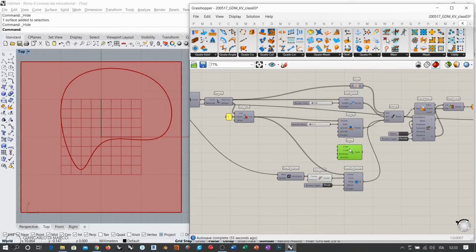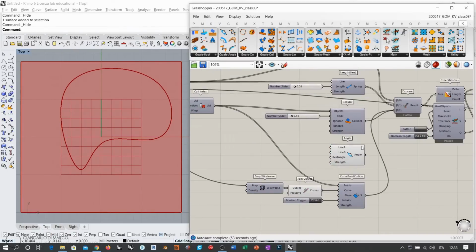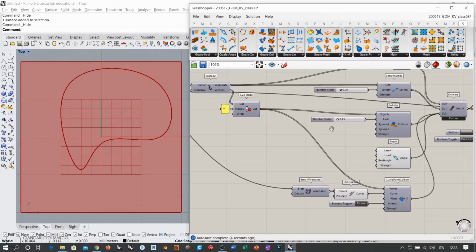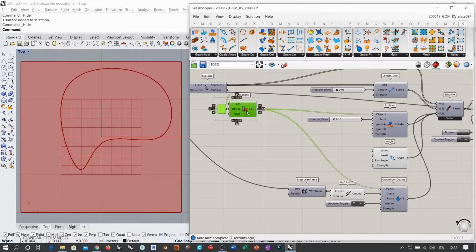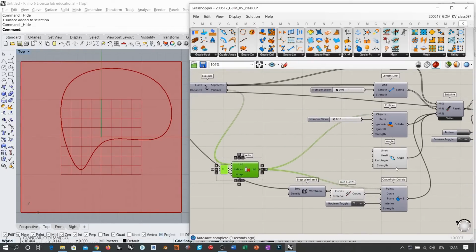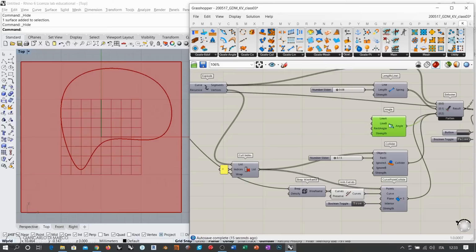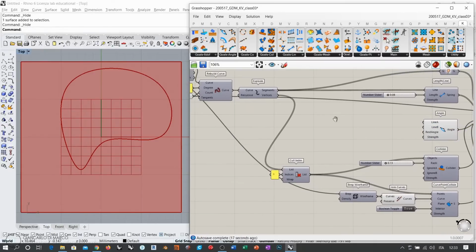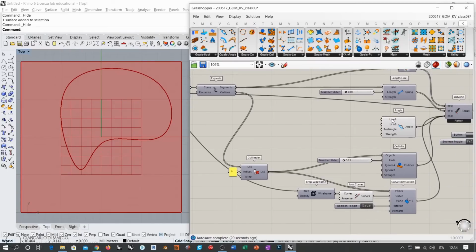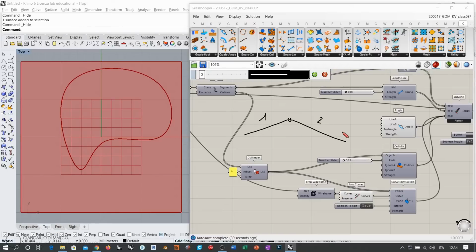I'm going to use this goal here. This is a non-geometrical goal, so it will be connected to the same input as the collider and the curve point collider. So they are all constraints basically, and I will move this here eventually, so collisions are going to stay together here, and I'm going to tweak now the angle condition. So angle must be set between two segments, and all of our segments are here. So what I need to do is adjust the angle between segment 1 and segment 2.